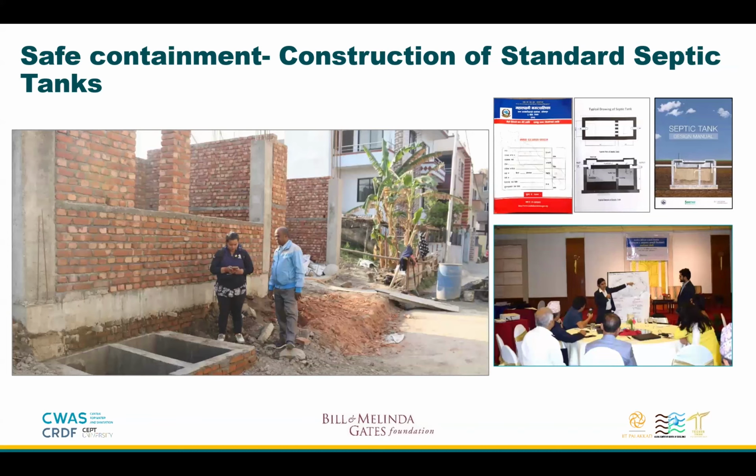So here is a glimpse of the assigned field coordinator, the field monitoring person, who goes to the field, and with the help of the sanitation app that has been developed in the municipality, monitors the constructed septic tank and enters all the values that meet the standard guideline. A standard septic tank design manual has been developed as well, according to which, if the household meets all the criteria of the standard septic tanks, only then is the building completion certificate provided.